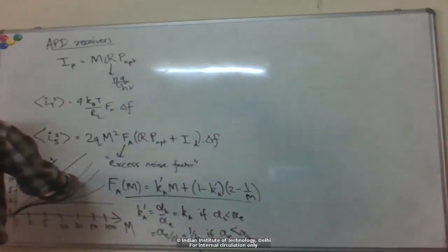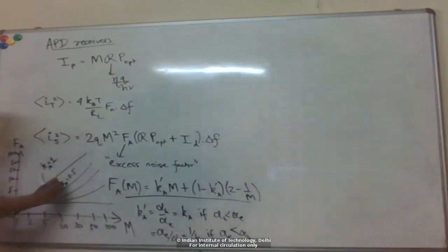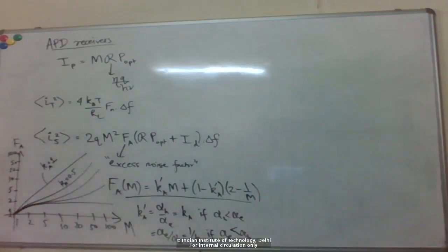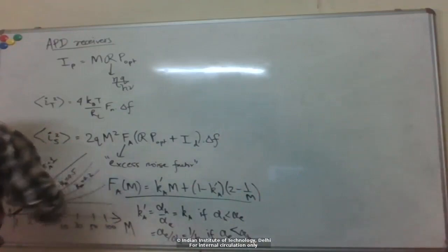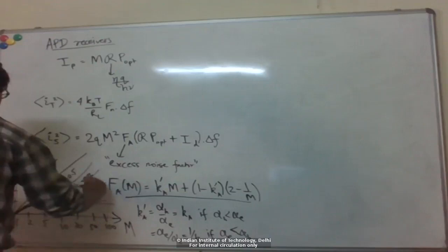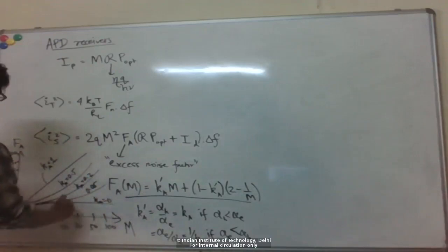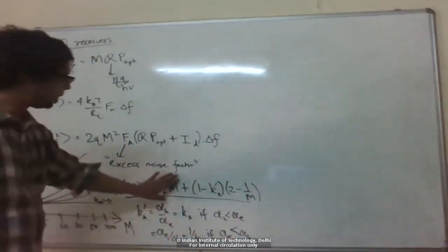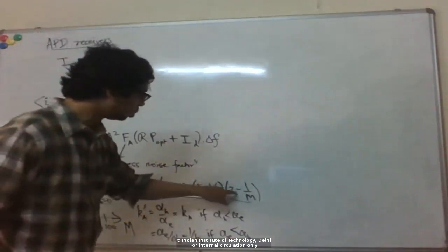Okay, so this is Ka equal to 0.5, right? So we saw that for the InGaAs photodetectors that we use, typically we are around this value of Ka. 0.2, 0.05, and then the other limit Ka equal to 0. Basically, if Ka is 0, now you only have the second term, which is 2 minus 1 over M, and then for large M that saturates to 2.